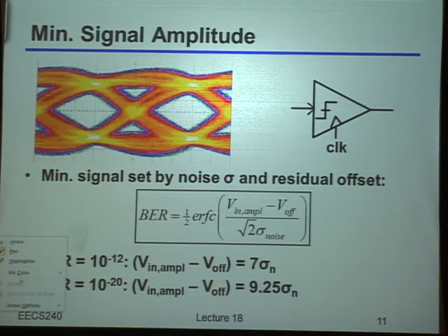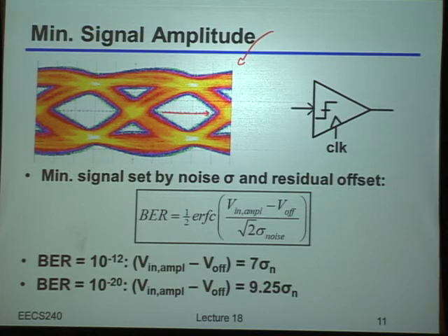When we build that very simple receiver, assuming this is something like a differential link, then if I look at this so-called I diagram, which, as a reminder, is me taking all of the received bits and overlaying them on top of each other in time, this gives me an idea, on each individual bit, both of how wide it is in time, meaning how wide the region is where I can sample it and still get roughly the right answer, as well as in the voltage dimension, at any given point in time, how far from my receiver threshold the incoming waveform is going to be. Yes?